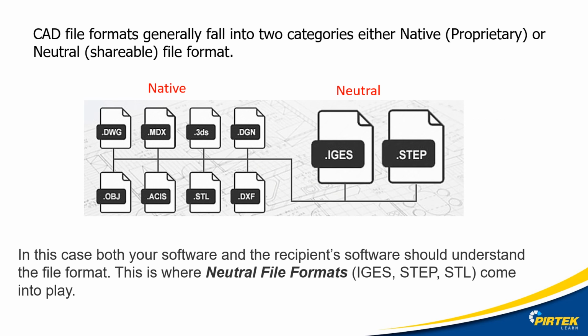CAD file formats generally fall into two categories, either native, which is proprietary, or neutral, which are shareable file formats. In this case, both your software and the recipient software should understand the file format. This is where neutral file formats like IGES, STEP, STL come into play.